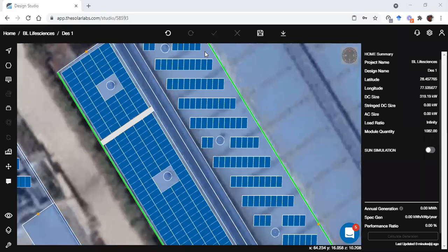Okay, so regarding the safety line, it will be placed there permanently, because it is not like that once you place the panels, there will be no need for safety line. Once you place the panels, you need to clean them. There is the maintenance part. So for that purpose, it will be permanently there, because when someone is going to clean them or for the maintenance part, they will need to rope themselves to this safety line.